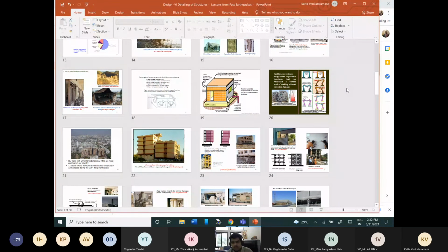As you know, the earthquake varies from place to place, also depending on the ground conditions. For example, if you consider the plotting of the Bhuj earthquake with another Taiwan earthquake, or say the Niigata earthquake, there will be a variation in the frequency content and also the amplitude and so on. But if you are considering the specific characteristics of a given location, for example, if you are constructing in the Bhuj area and you know the Bhuj earthquake and you also have some records of the previous earthquake, then you can use that as the input to the design.